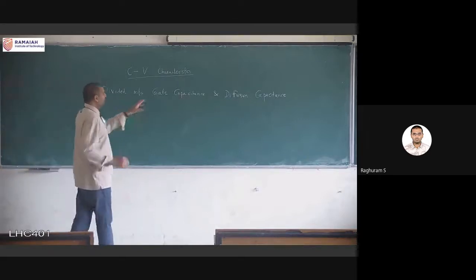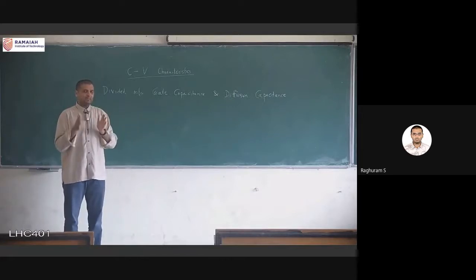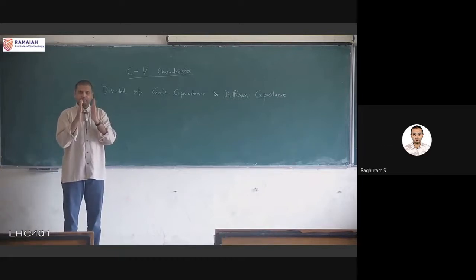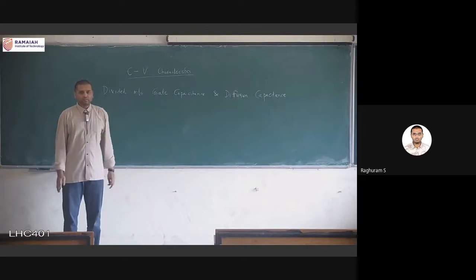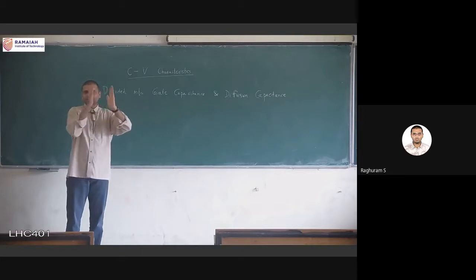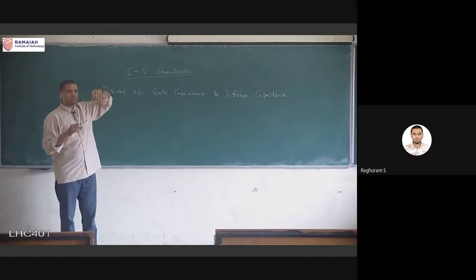But mainly, gate capacitance means there are two terminals. In all the analysis, we will simplify the capacitances into a parallel plate capacitor. A parallel plate capacitor means there should be two parallel metal plates, and in between there should be a space separated by an insulator. In each of these cases we have to see which two terminals are forming the parallel plates and what is in between forming the insulator. Gate capacitance means one of the parallel plates is always the gate terminal. For example, a lot of times we draw it with the gate on top, right?